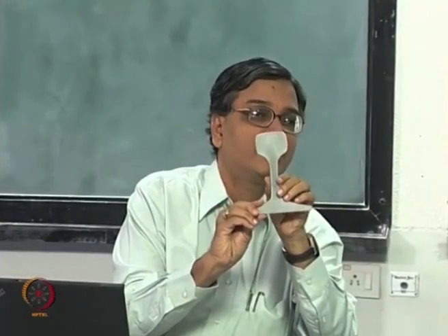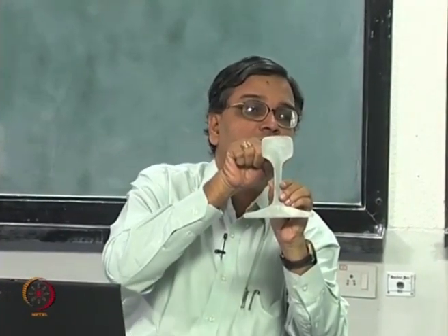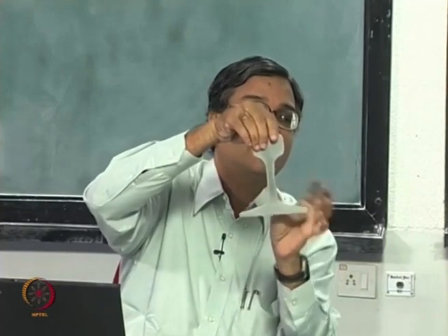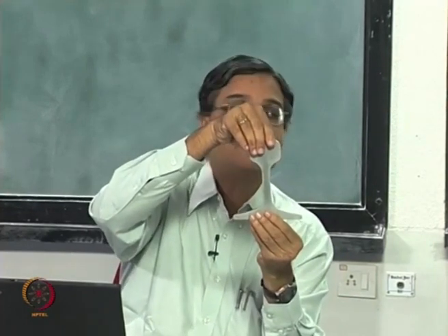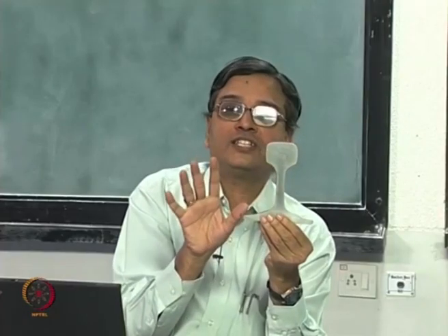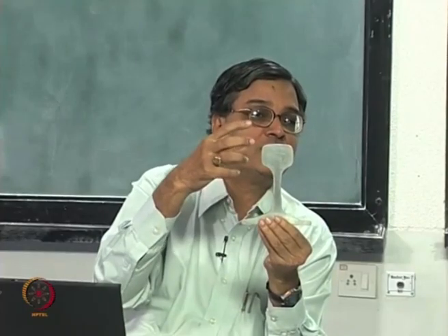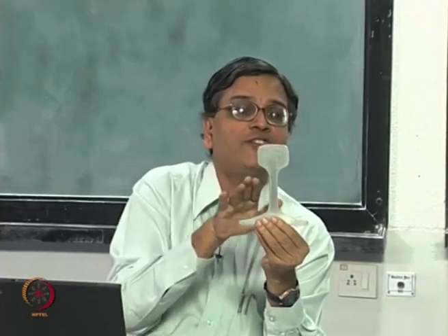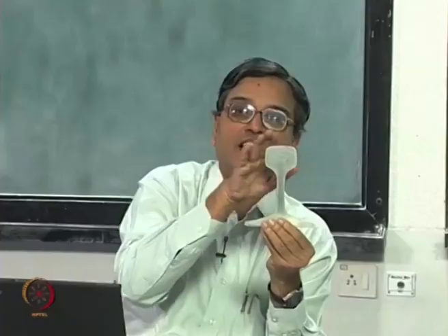If you go and see a rail cross section, you do not have a square block, because you know that this is subjected to load on the top face, and you know it is essentially transmitting a bending load. Since the inner core is not participating, you have removed the material. So what you have done is, in your analytical approach, you have not solved the problem of the rail to start with, but by understanding bending, that the stresses vary linearly and the inner core is not contributing, this is effectively utilized in arriving at the shape of the rails. Okay.